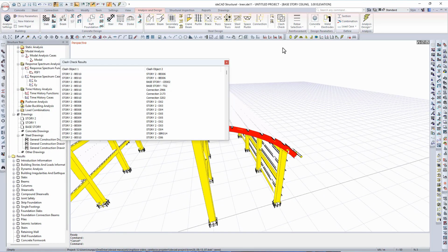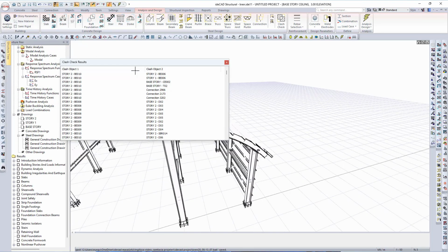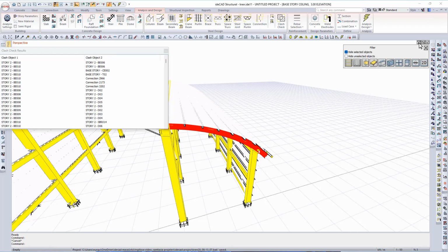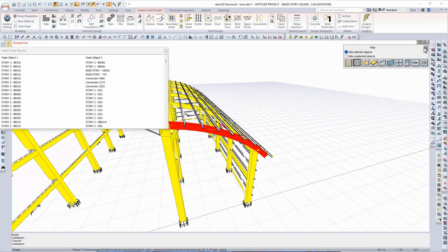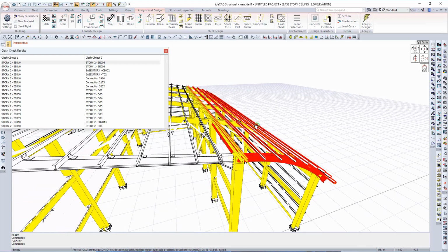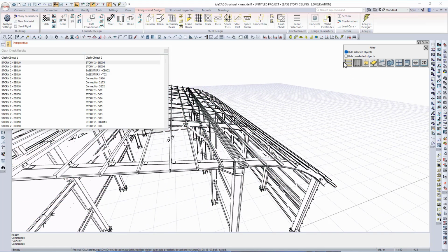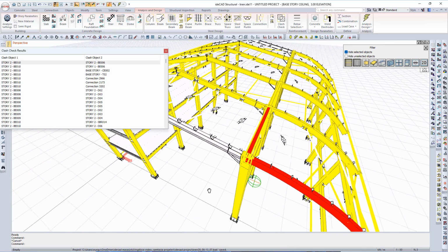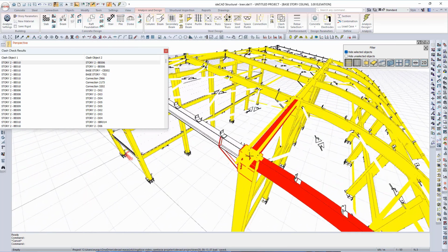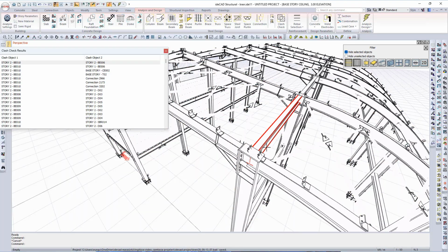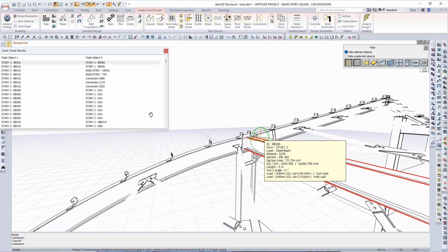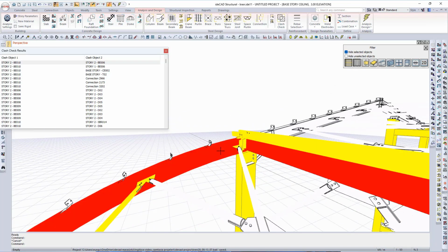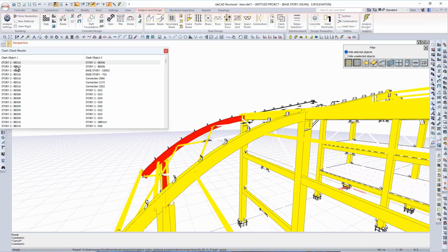After running the check, a detailed clash check report has been generated. To better visualize the issues, I filtered out the claddings. Then, I clicked on the first row in the list, and as you can see, the two clashing elements are automatically highlighted in red. Zooming in a bit, we can clearly see that the beams connected to the column along its strong and weak axes are intersecting with each other. This is because no connection has been assigned between either beam and the column.